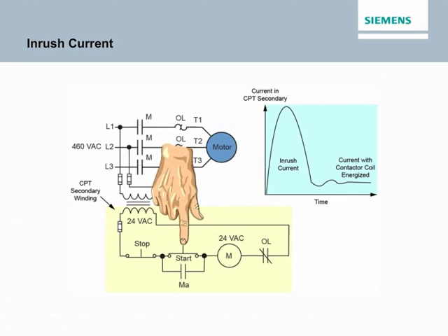When a control circuit energizes, as for example when a motor starter contactor coil is initially supplied current to close the contactor, the current required from its power source rises to as much as 10 times the current required to hold the contacts closed. This inrush current can last for up to 50 milliseconds, depending on circuit characteristics.